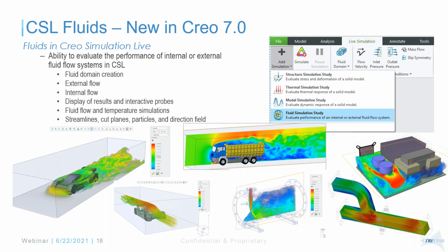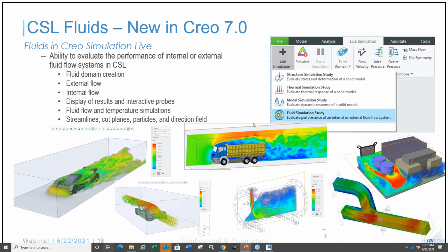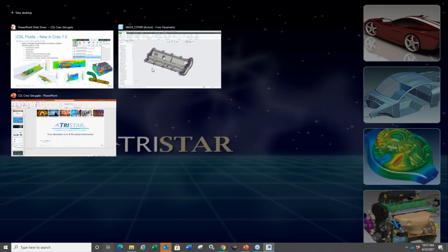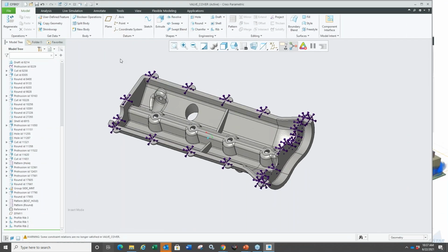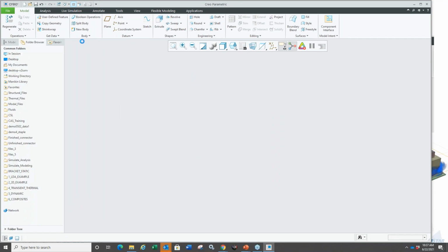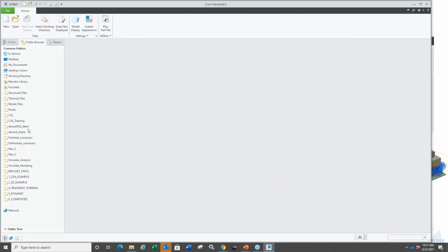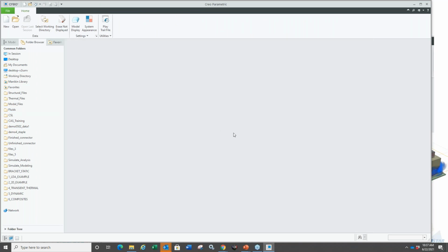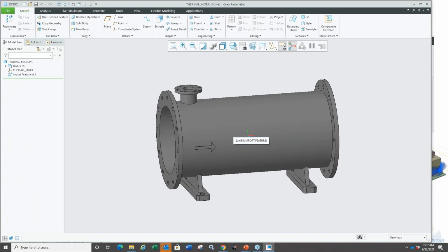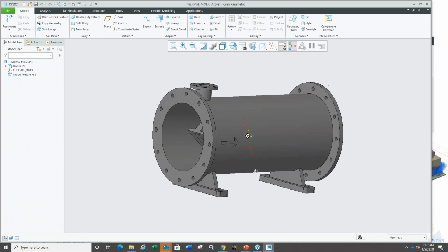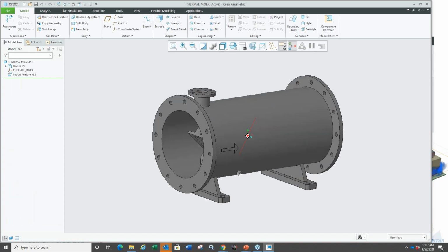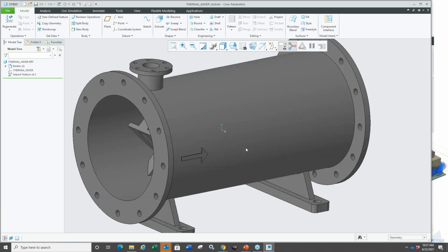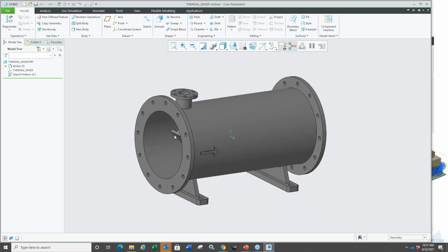feedback, right? So when I say quick feedback, if I go to my Creo here, and let's say I want to get to another model here. I want to go open up another part. This works, by the way, in parts and assemblies to create your fluid domain. In many CFD software, creating the domain itself is a big deal, right? How do you create an internal fluid volume? I have a thermal mixture, maybe water mixing. You have hot water, cold.